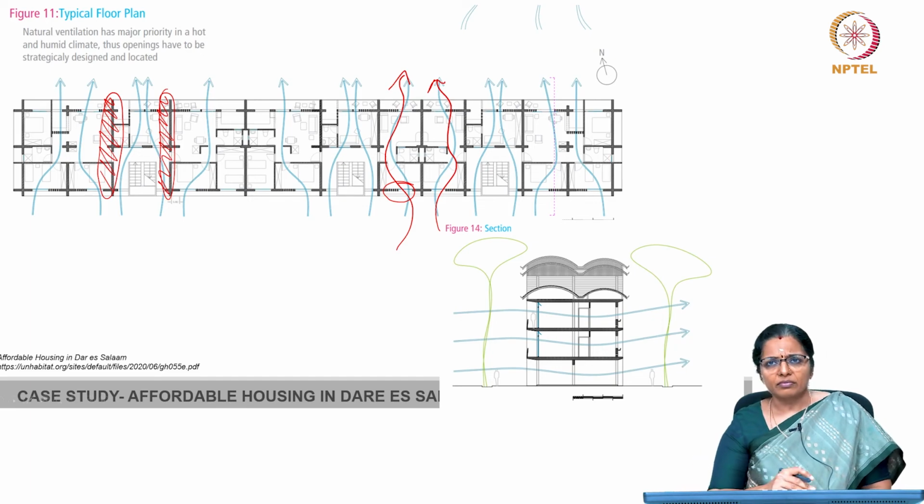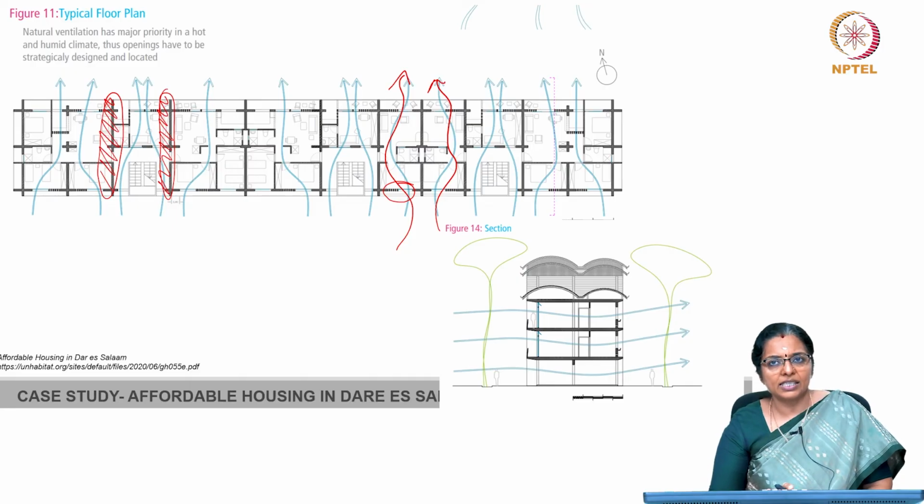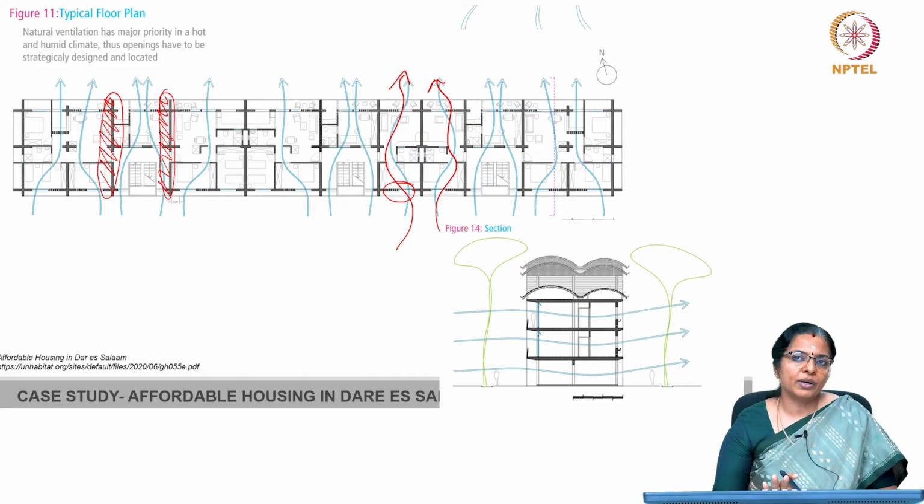Now, permanent ventilation vents at different heights and a continuous open air chamber on the roof enhance airflow, and the open plan layout of the living space minimizes airflow resistance, creating efficient flow paths for cross ventilation.